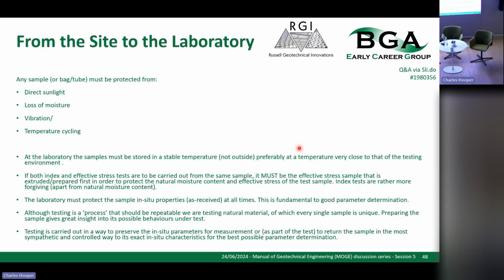So I've heard people say, oh, we all know the values for London clay. Well, my answer is I don't. That's why I test them, because they are different. You can average things out a little bit and have a ballpark, but they're never the same. Please beware of that.